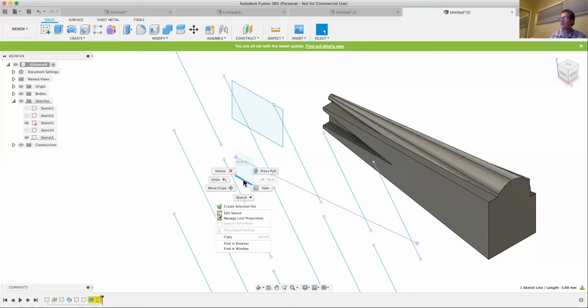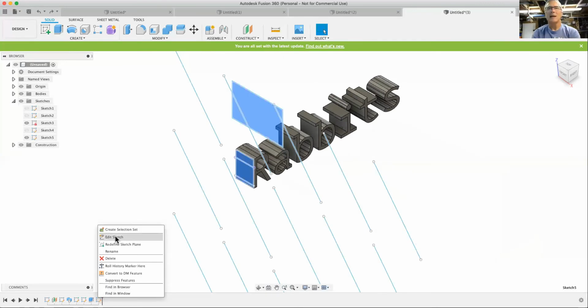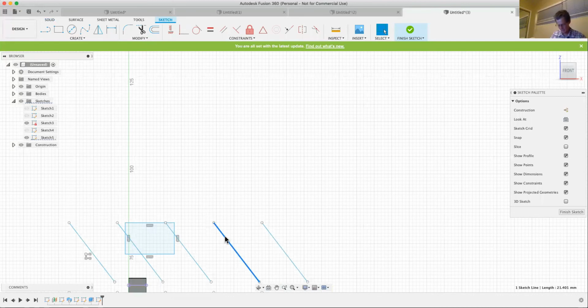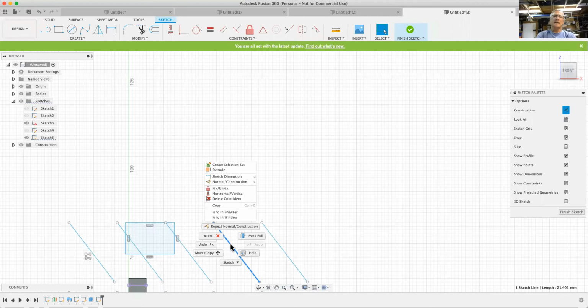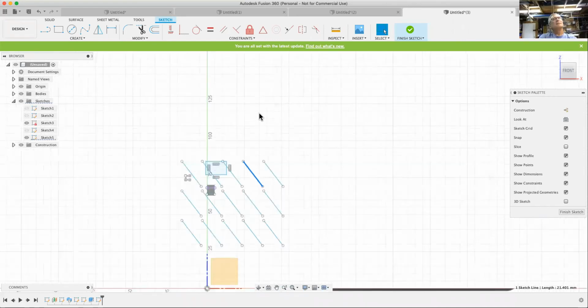Well, you can pick a line when you're in sketch mode, click on a line and then hit X and it turns into a construction line. That's the shortcut. Got it, that's all I was asking, thank you. I usually find it in the menu. I'm trying to avoid learning too many of the shortcuts because I'll lose you guys.